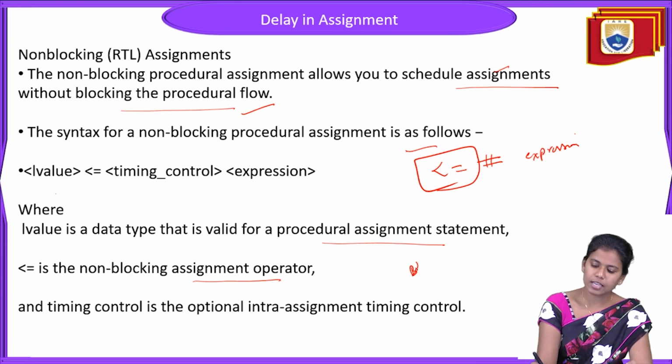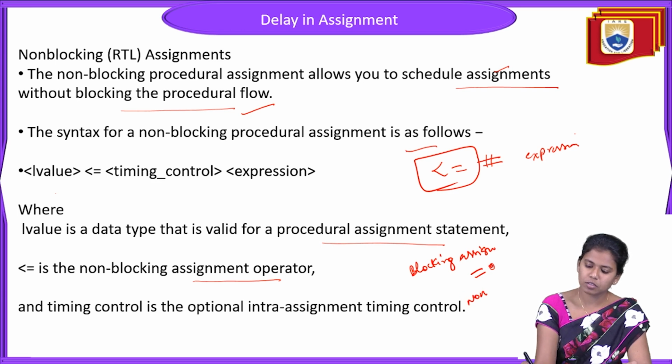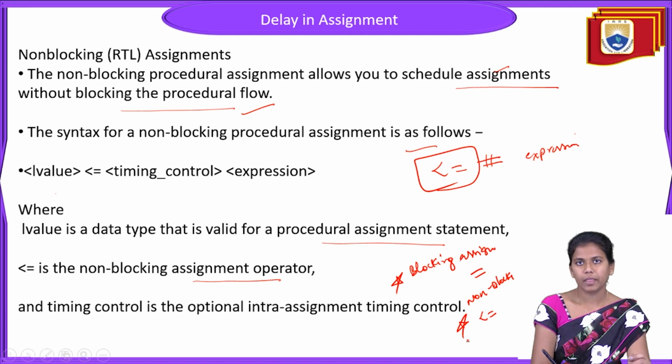So for blocking assignment, equals to is the operator. The assignment operator is equals to. For non-blocking assignment, it is less than or equals to. So this is an important point to remember.